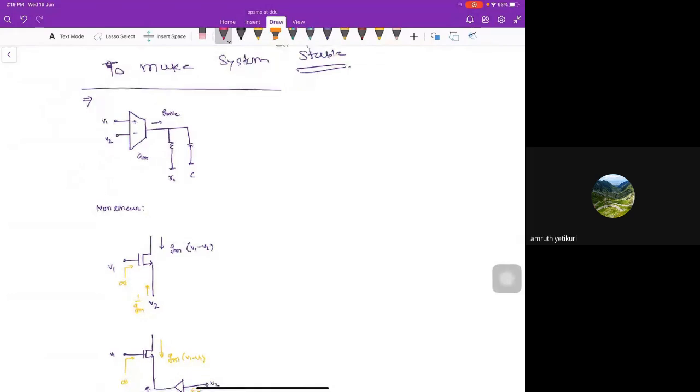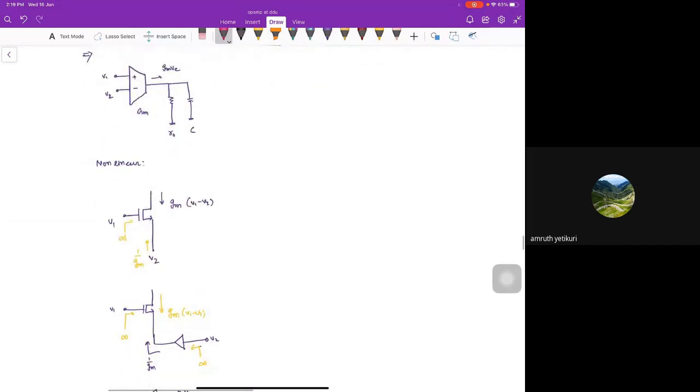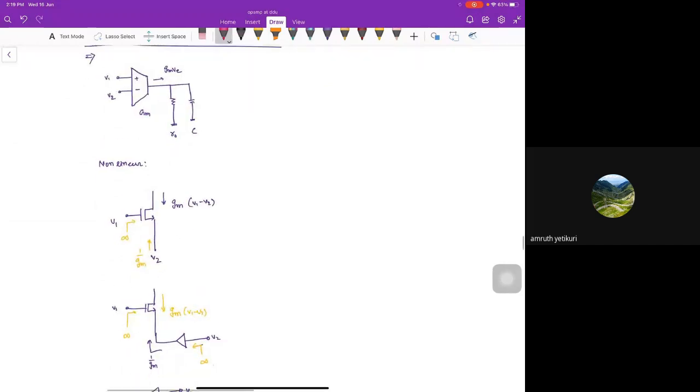So here, this is an operational transconductance amplifier, that we want to build, right? So we need two different inputs. Let's say the simple MOS devices, we have V1 applied here, and V2 is applied here. I will get the current gm times (V1 minus V2). That's the requirement satisfied. That's why I want the current equal to gm into VD.